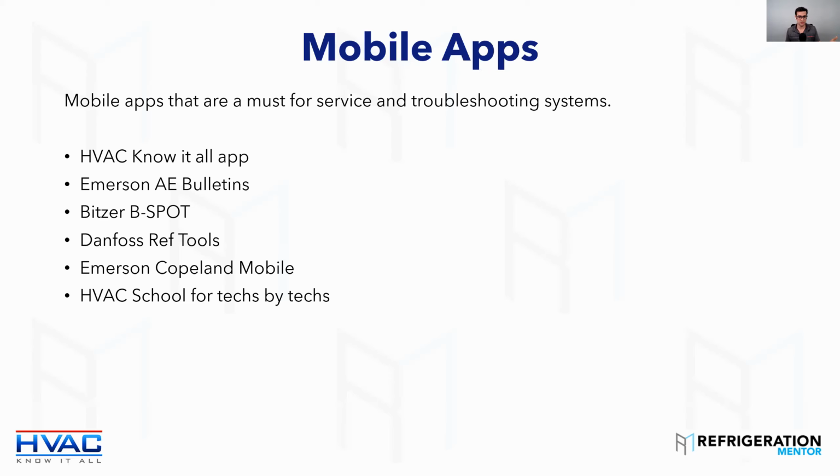Anybody know? Throw it in the chat. Unmute yourself. 225? 100%. That's what Copeland doesn't want to see over, 225. When you look at Bitzer, what does Bitzer say, 6 inches down? Don't know that one? That's okay. It's 250. So there are different temperatures.